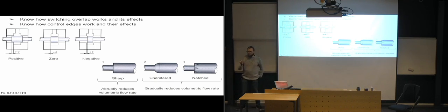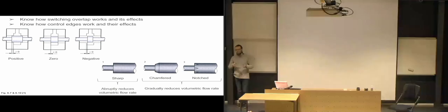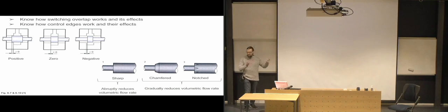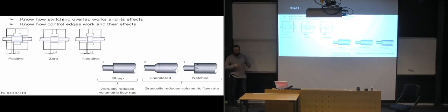The shock can create pressure peaks, basically. But the main problem with the shocks is that you get vibrations moving through your system, so through your hoses, through your pipes, and through their couplings. And if this happens very often, it can lead to fatigue stress in those components, which can lead to them breaking in the end. So you don't want it happening often, but for example for an emergency stop, they are very useful to have.